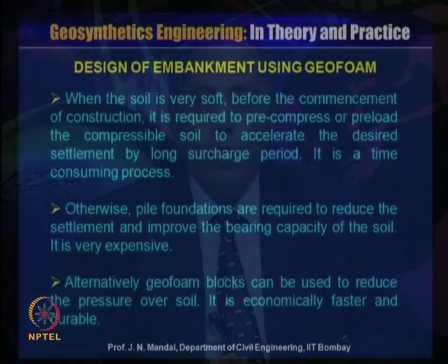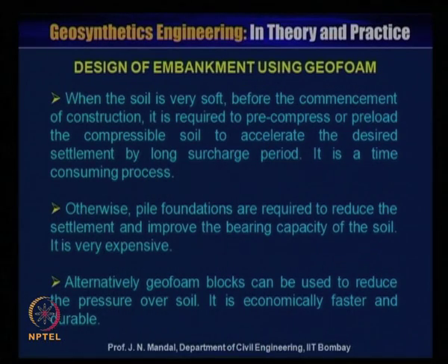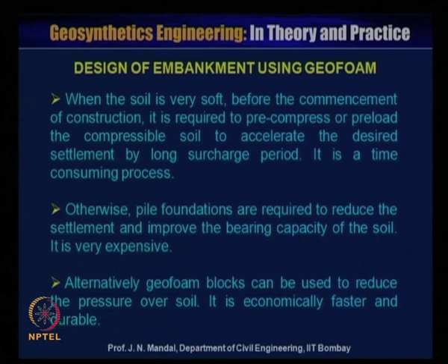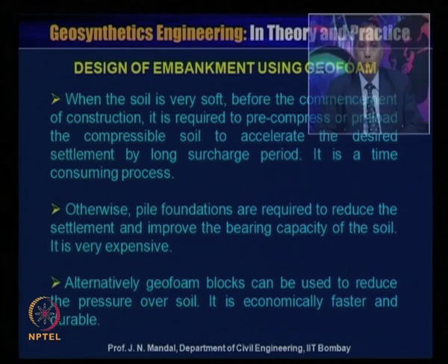Now, when the soil is very soft, before the commencement of construction, it is required to pre-compress or preload the compressible soil to accelerate the desired settlement by long surcharge period. It is a time consuming process.